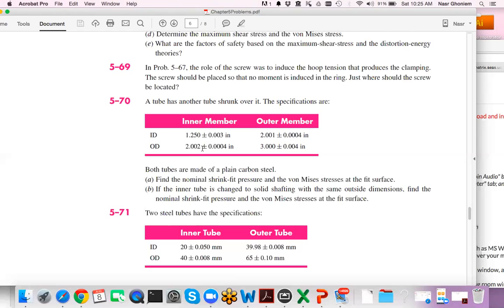1 mil. And notice some of you have assumed that the difference is the delta, but delta is actually the difference in the radii. So we have to see the radii here. The difference nominally is 1/2 mil between these two, the interference. And then you have the extreme, 4 mils plus or minus. The outer doesn't matter here, because we're not going to do anything. What matters is really the ID of the outer and the OD of the inner.